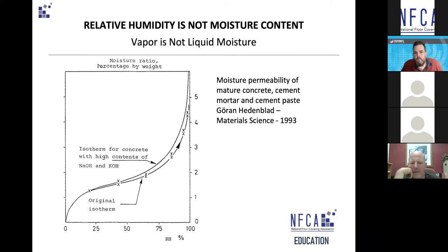William, who just spoke there, has put a lot of this into practice. He has developed moisture content limits for the different products that they produce, for different adhesives. And it's a lot simpler in a sense to point to moisture content than relative humidity. But our preference is to measure both.